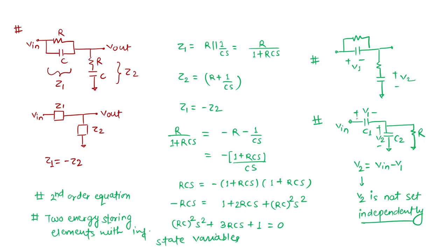So whenever this particular combination comes, one state variable means only one pole will be there. Two state variables means two poles will be there. From V in to this V2, you can see these V1 and V2 are independent. Because of dependent state variables, only one pole is there. This thing we can see. This is my C1, this is my C2, and it is my some R naught. I am capturing my output voltage here, and here I am giving my input.